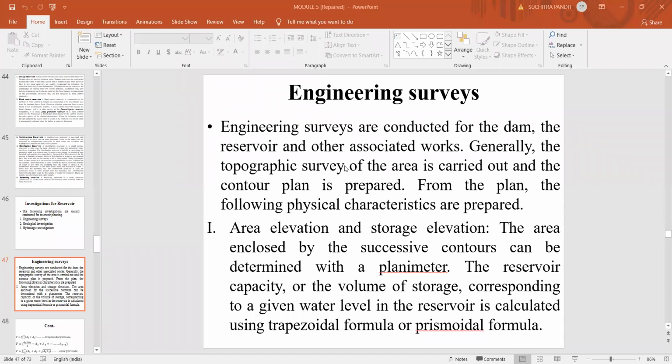You have done a new tank project in your extensive survey project, wherein you selected a place for constructing the new tank. Then you calculated the height of the new tank to be constructed, and you also carried out the contours on the upstream side of the new tank, so that you get the area and also the depth, which gives the volume of water to be stored on the upstream side. And you have also carried out the canal alignment, right bank and left bank.